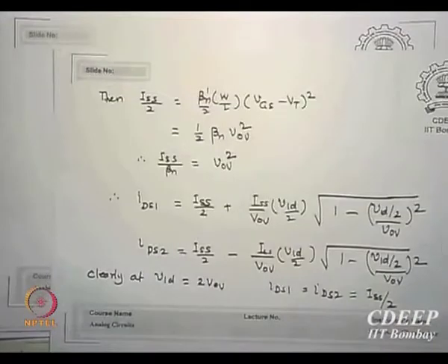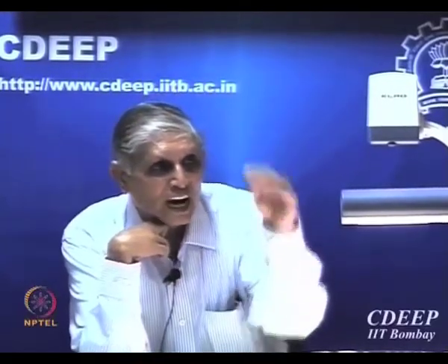That is why amplifiers are small signal amplifiers. Is that clear? They are called small signal amplifiers. Yes, VOV will matter. The idea is that in this region where VGS minus VT is holding, the linearity is holding. That is how we started with this assumption. If the curve goes away, essentially what you are saying is true. But at any point wherever I fix it, around that I can assume linearity. Is that correct? But if that signal expands, then I am not sure whether it is linear or not.